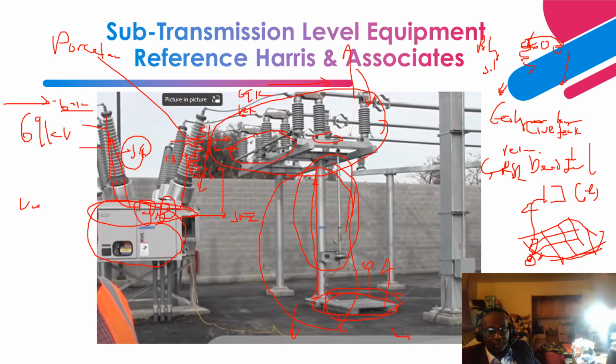Okay. So as you can see, on the surface of the substation, we have rocks, we have gravels. All these are added to add an additional layer of resistivity. They call it surface layer resistivity, right? If they do all the analysis and found out that the step and touch potentials, right? Step and touch potentials, right? Okay, so the step potential, right? If your leg is right here, right?